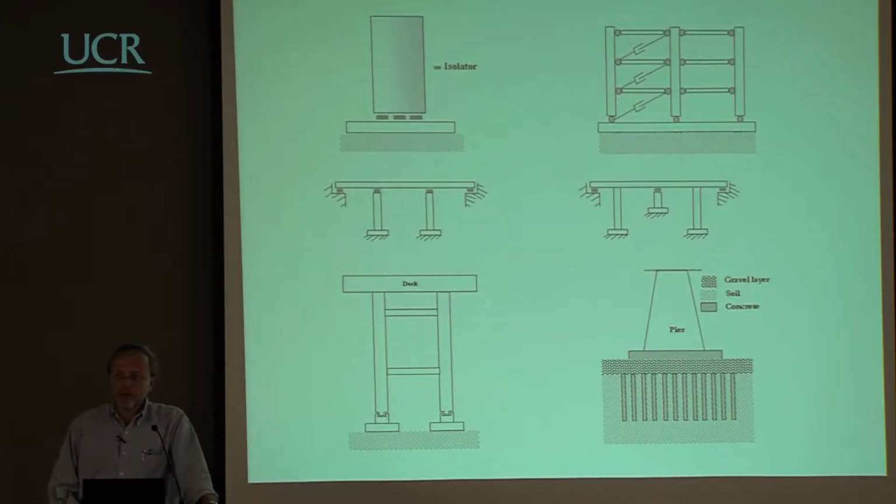And if you think of the structure in general terms, in the direction of making the response more regular, you could even conceive something where you are not isolating all the piers, because you want to use the isolation also to make the more stiff foundation pier systems more flexible. In such a way, the deformation of the deck will be much reduced. The deck will not be cracking. The reaction at the abutments will be controlled and so on.